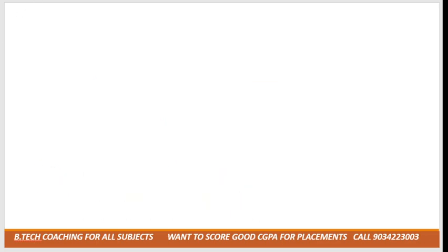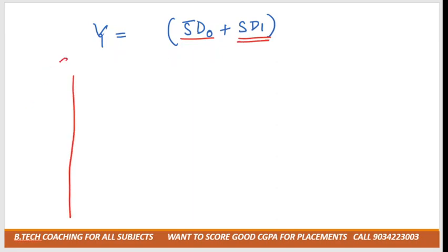Now what we need to do? We have to draw the logic gates using this expression. We got E(S bar D0 plus S D1). We'll ignore the enable E because obviously it must be on in every case for the multiplexer to work, right? So we have to draw the logic gates for the rest. Suppose we have one line S, and we need S bar also, so which gate do we use to make S bar? NOT gate, so that would be S bar.